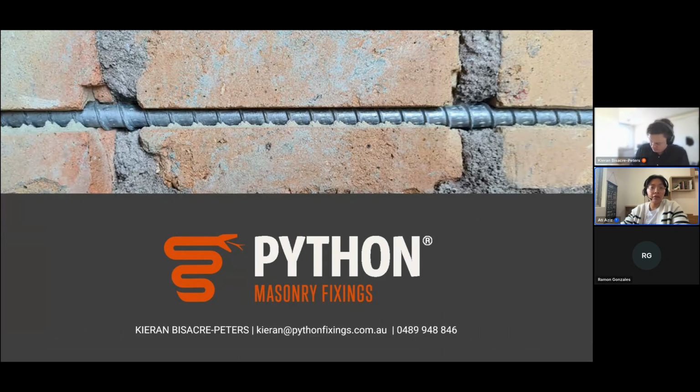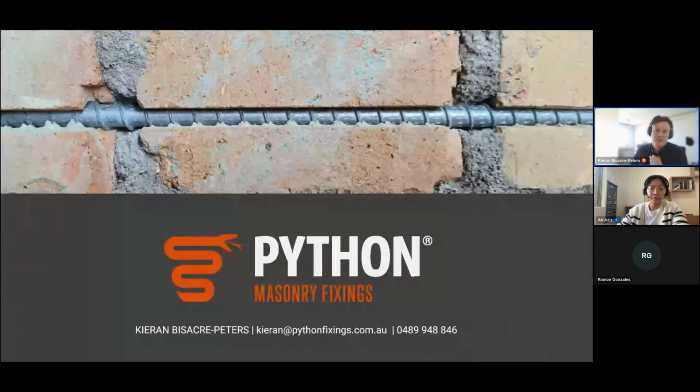From Avandi: for the pre-tension rod system for retrofitting brick chimney, what is the fixing method between the top plate and the chimney? The fixing method between the top plate and the chimney is compression. I believe it was just sitting there in that test, but you could easily fix that down with some small mechanical anchors vertically into the brickwork just to hold it in place and do a calculation on the spacings and embedment that you need.